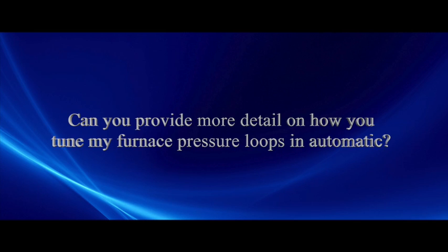And so you put that in, and then you ask, did I like that slight little oscillation? If not, then you back off and go with a little bit less gain. And then you test it again. Then you test it with the new gain, with the new reset setting, and just make sure that the oscillation is very little, by making a little set point change.